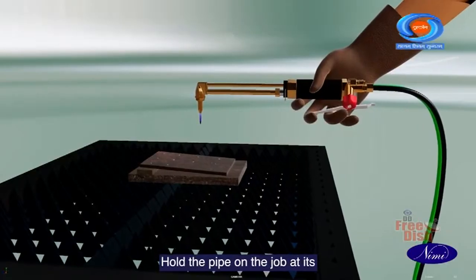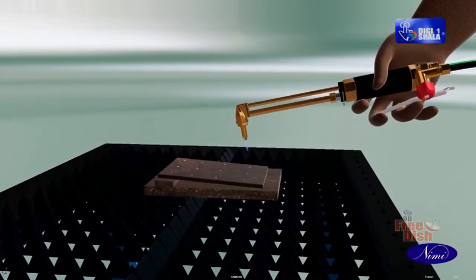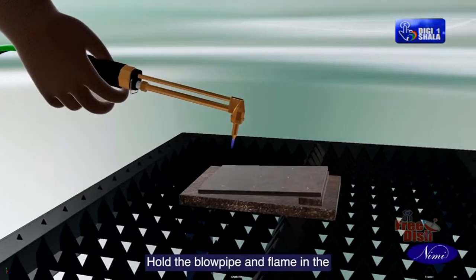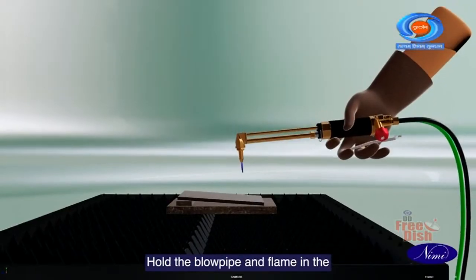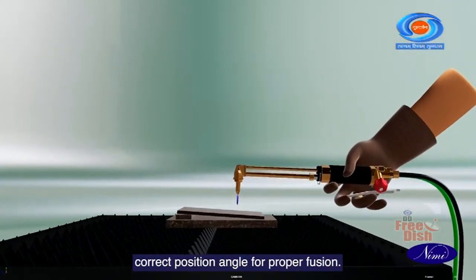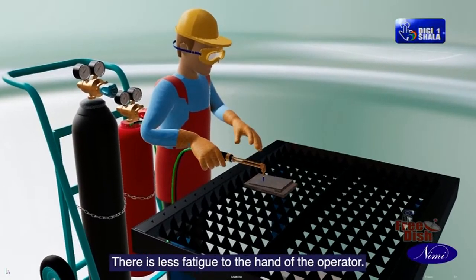Hold the blowpipe on the job at its right hand end at the required angle. Hold the blowpipe and flame in the correct position angle for proper fusion. There is less fatigue to the hand of the operator.